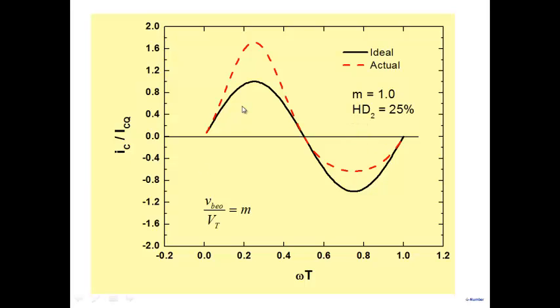So you are saying that because of the nonlinearity, the sinusoidal collector current itself is distorted. And if this distorted current flows through my RC or RL, obviously it will build up a distorted sinusoid. Alright, so I will get a distorted output voltage here. How distorted will it be? It depends on how large an input voltage I apply.